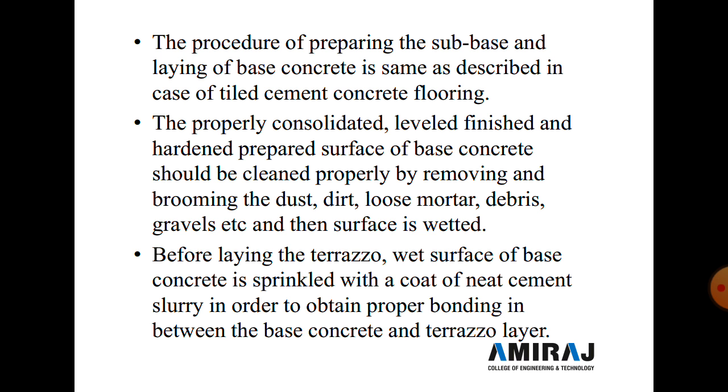So here the subbase is a well compacted layer of soil, and the base course is a mixture of cement and aggregate in a proportion of 1:3:6 or 1:2:4, and the properly consolidated, level, finished and hardened surface of the base concrete should be cleaned properly by removing dust, dirt or loose mortar, and then the surface is wetted.